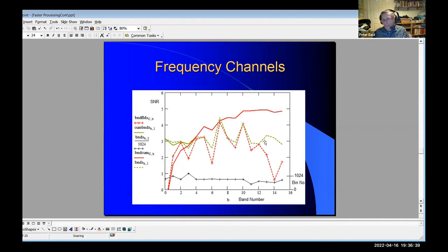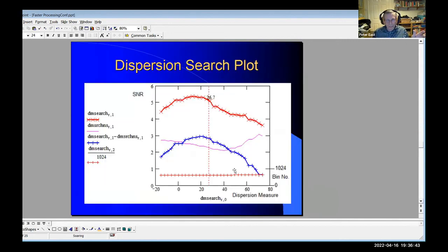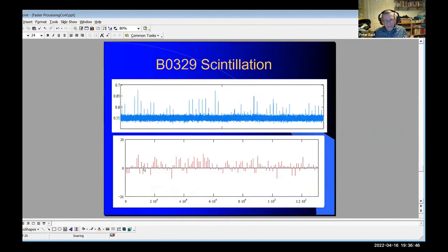Now, if I do that with sections, I find that when I'm doing the sections, this is telling me what the signal to noise ratio is in each of the sections. It's not telling me the signal to noise ratio because it's not in signal to noise ratio scale. But what I can do is blank that section, that section, that section and that section, and my signal to noise ratio would go up, and it does go up. But you don't know whether what you're doing is removing a bit of signal in there, or a bit of noise that's pulling those up. You don't know.